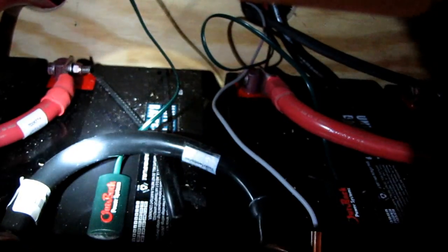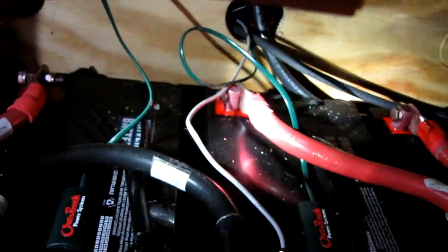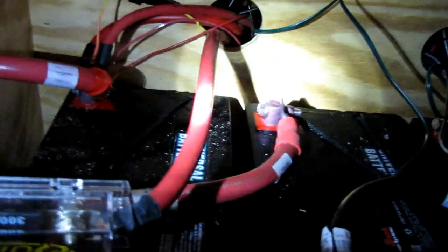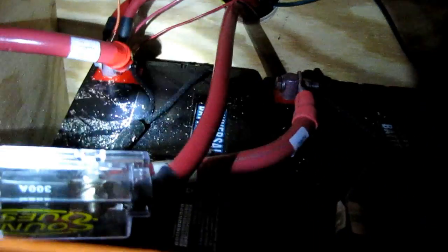Don't need that big really on 24 volt. I mean, in 12 volt you would need them, or 6 volt, but I got them in series parallel, but I got them because I just used what I had. Oh, sorry about that, y'all. But anyway, that's my battery bank. I got 6 AGM batteries at 90 amp hours apiece. So at 24 volts, that'd be 270 amp hours. And that's all you really need.